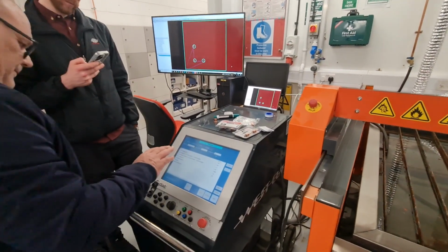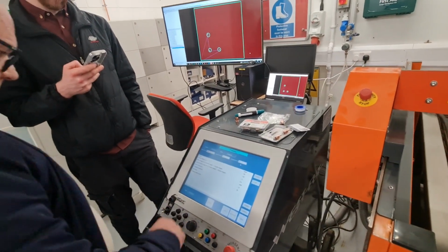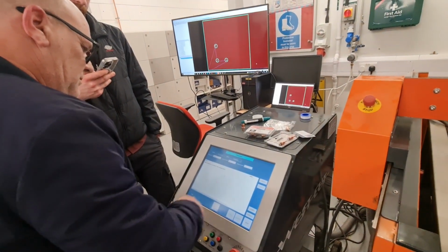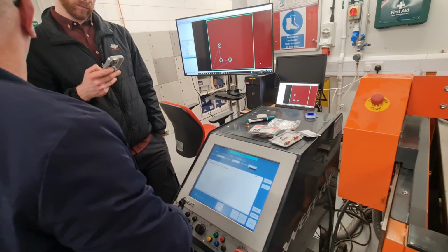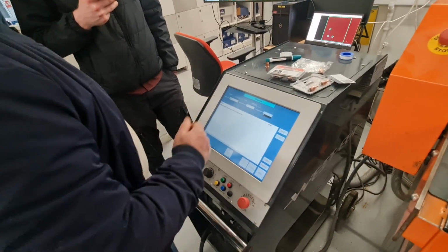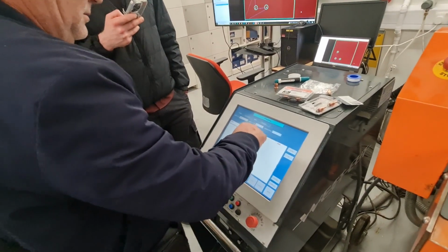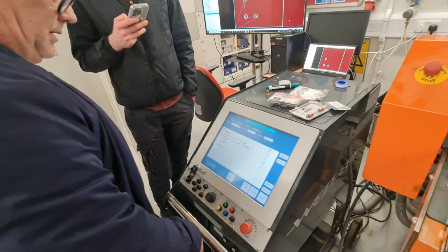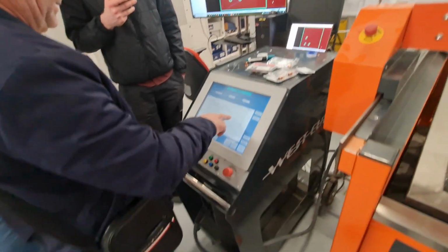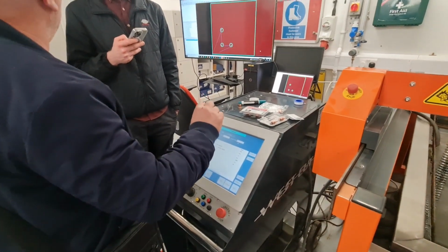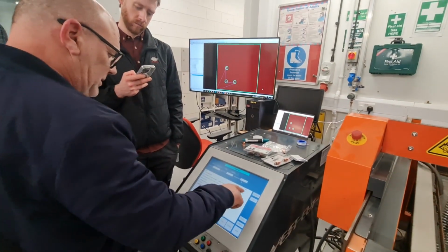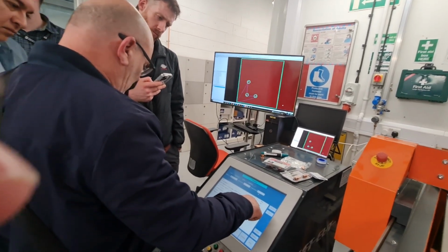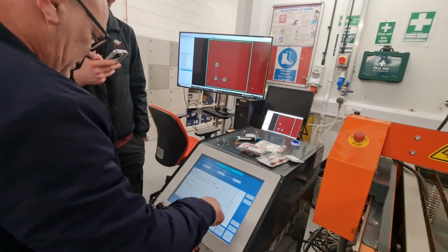Now let's say I will make a mistake here, and instead, I want to go 16. The machine will tell me you can cut it with 65, you can't cut it more. Okay? I'm going to change it. Now we have different parameters because the material is thicker and the tool is different. So the set arc voltage is 130. This I really need to check, it's 1.5, and the feed rate is 1800.